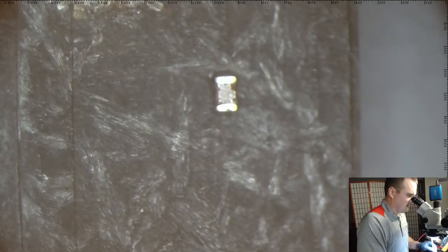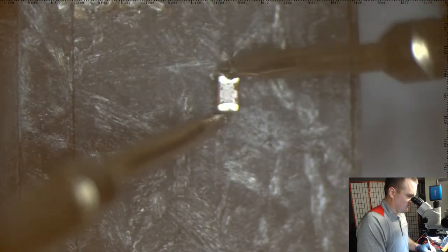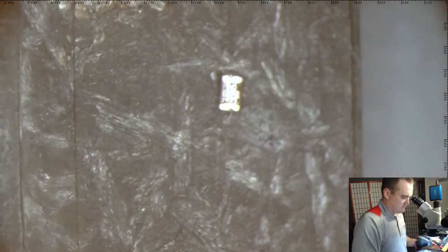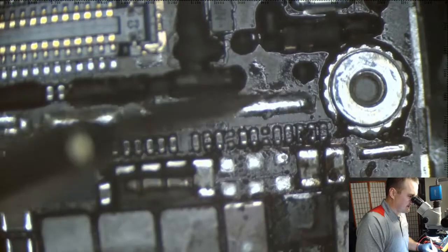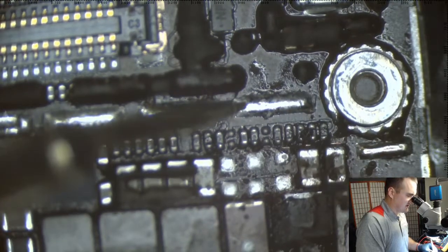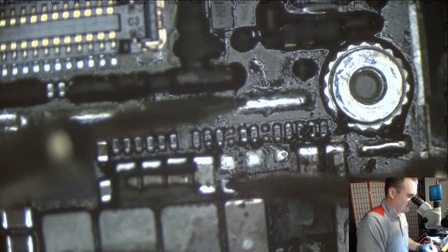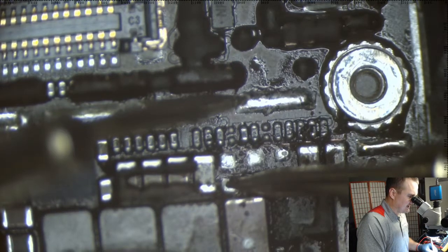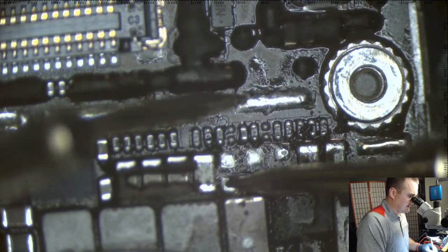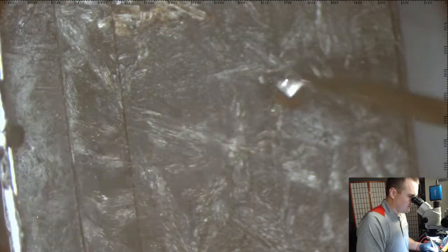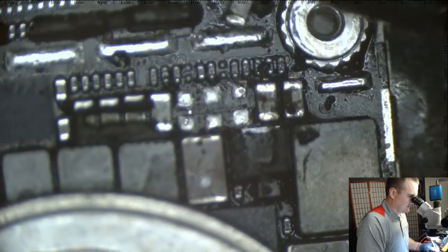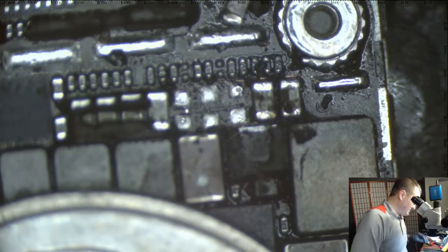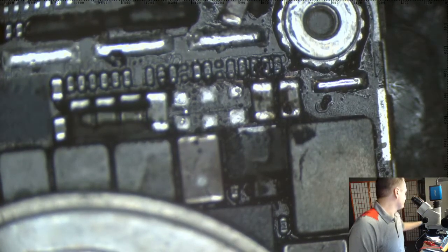Naked capacitor should give you OL. You shouldn't get any beep. Let's test that theory. Red on ground. 550. That's what we wanted to see. That's what we needed the whole time. Okay, so worst case scenario came true. I had to pull all three to find the one that was at fault. I'm not mad, I'm just disappointed.